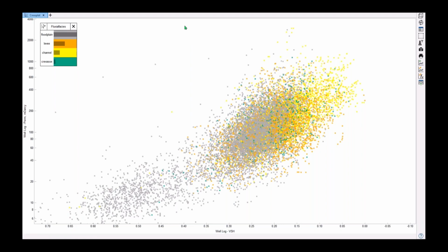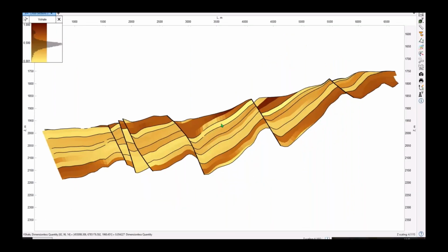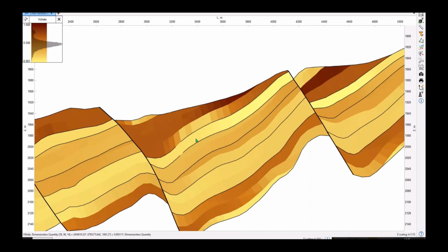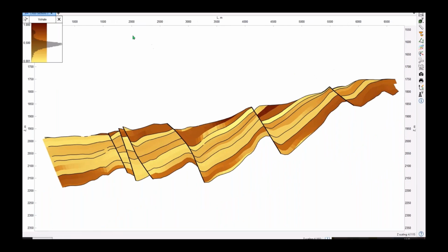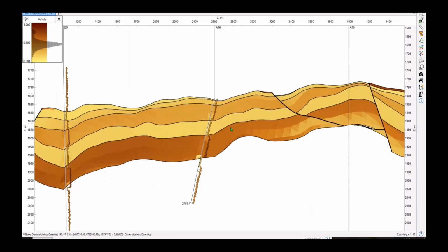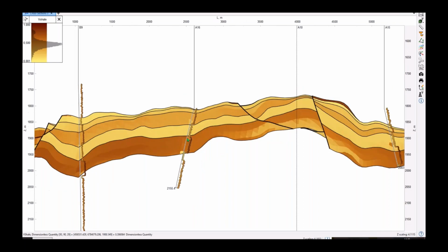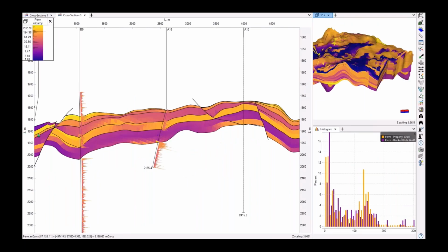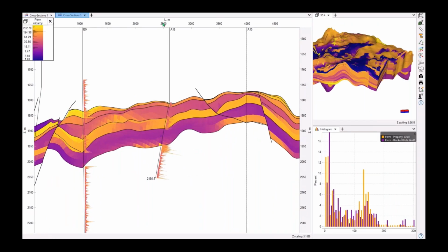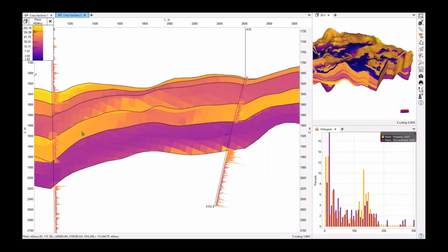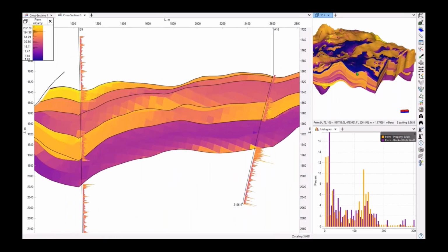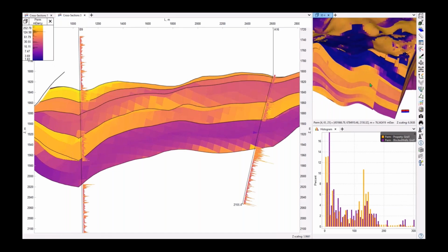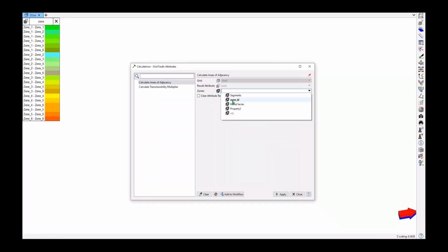So I'm going to go forward and co-create with them both and populate out my model. I've used my zone property and also my facies model to populate out my V-shale. We can see these nice bands of higher shale and lower shale volume. I can also QC this against my initial well log data, which we always want to do, of course. I'm plotting my well log data on my cross section with this, and then the same for permeability. I can say the correlation coefficient is maybe negative 0.7 for my permeability, and this just means that my V-shale and permeability properties are both tied together.